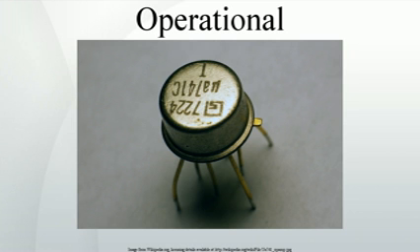Differential amplifier. A differential voltage Vin at the op-amp inputs, pins 3 and 2, respectively, gives rise to a small differential current in the bases of Q1 and Q2, Vin/2 hie hFE. This differential base current causes a change in the differential collector current in each leg by Vin/2 hie. Introducing the transconductance of Q1, gm equals hFE/hie, the small signal current at the base of Q15, the input of the voltage gain stage, is Vin gm/2.